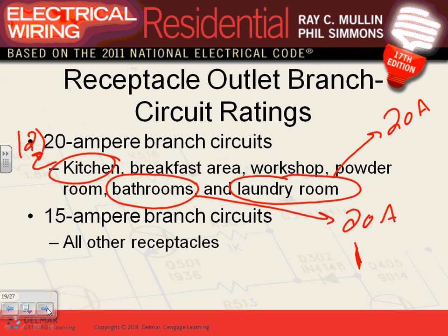For the bathroom, can I just steal the 20 amp circuit and feed the receptacle in the bedroom? You can, but it's against the code. Can I go to the laundry room and poke out and feed the receptacle outside from the laundry room? You can. I've done it. If it's not going to be inspected, it works, but based on the code you can't.